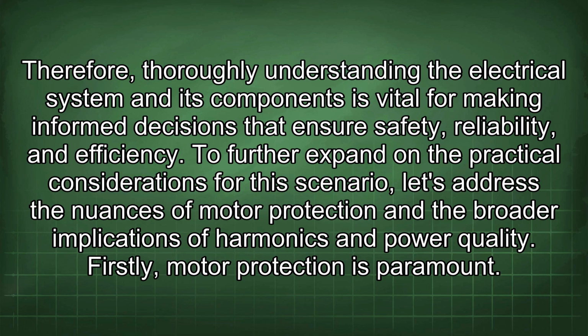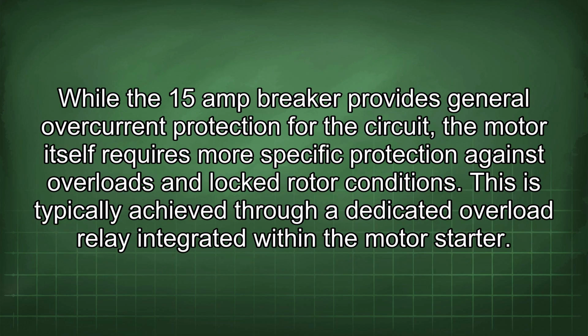Firstly, motor protection is paramount. While the 15-amp breaker provides general overcurrent protection for the circuit, the motor itself requires more specific protection against overloads and locked rotor conditions. This is typically achieved through a dedicated overload relay integrated within the motor starter.